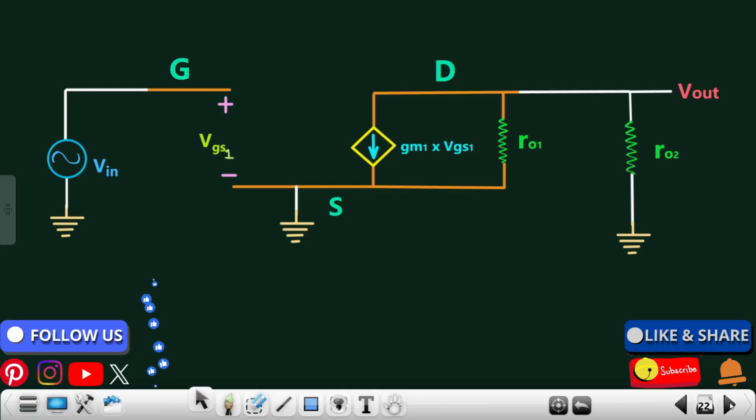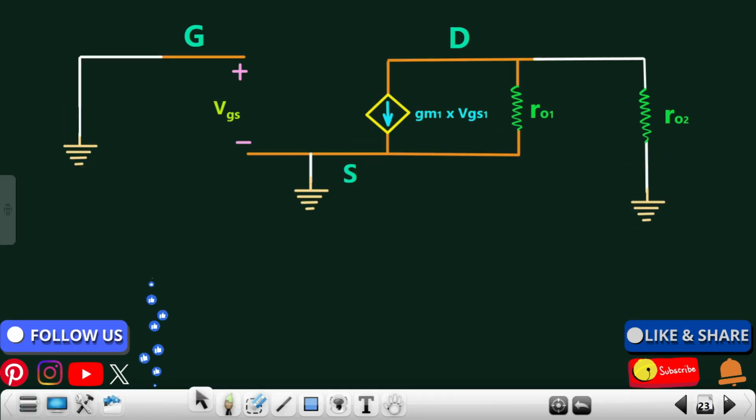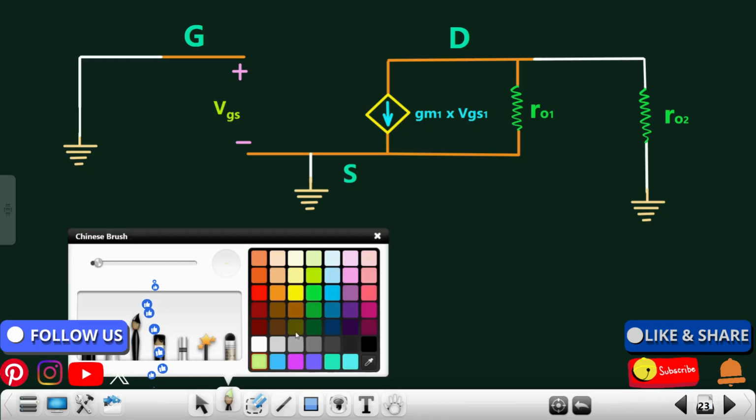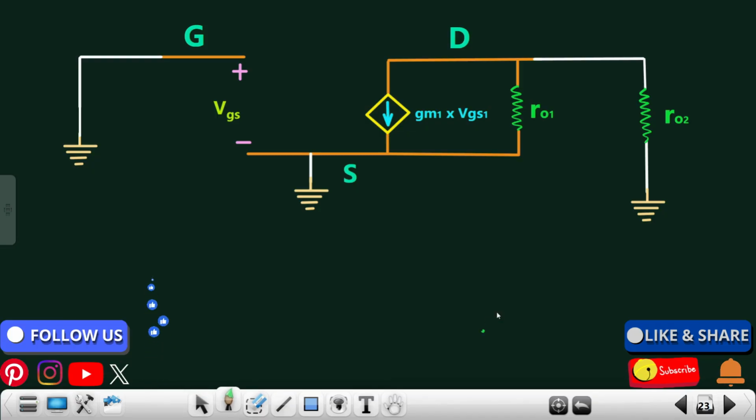Okay, now let's proceed further. First of all we'll deal with the output impedance because it is quite simple. What will be the output impedance offered by this particular model? For output impedance, short circuit the input voltage according to Thevenin's principle. So we try to look at the output impedance from this particular terminal, that is, this will be my Rout.